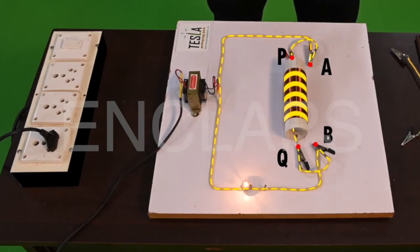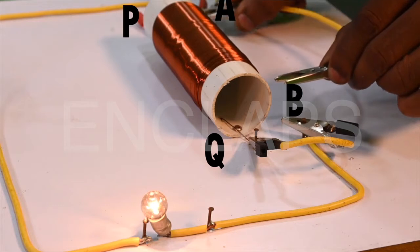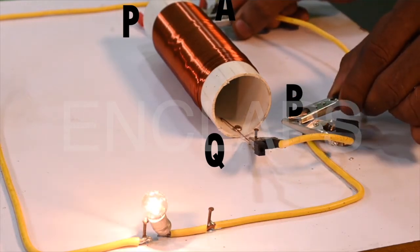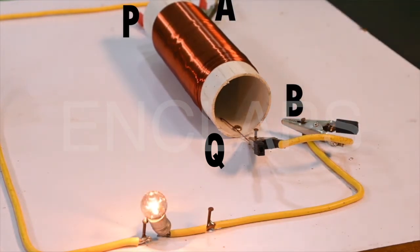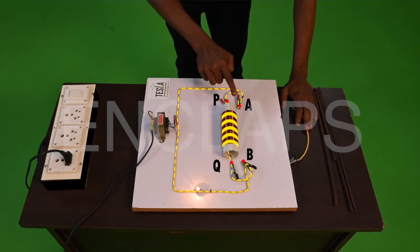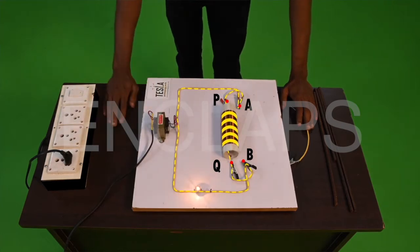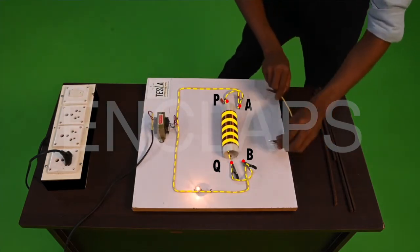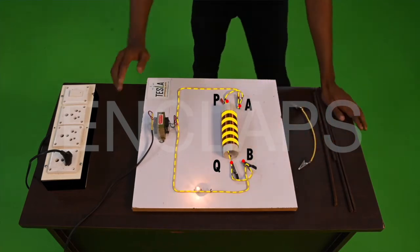What may be the reason behind this? Why did the intensity of the bulb decrease? Let's connect AB again for a better understanding. When current flows through AB, the bulb glows with maximum intensity. But if AB is removed, the current flows through the solenoid, which results in the lowering of intensity of the bulb. Here, the current flows from the transformer to P, to the solenoid, to Q, and to the bulb and back to the transformer. When AB was used, the intensity of the bulb was maximum. But when it is connected to the solenoid, the intensity reduces.